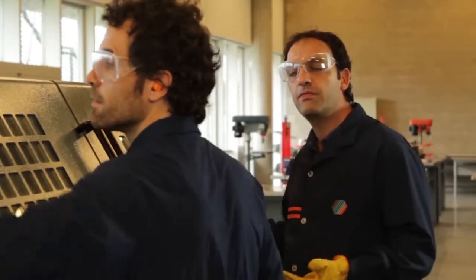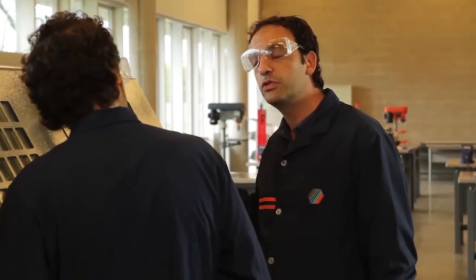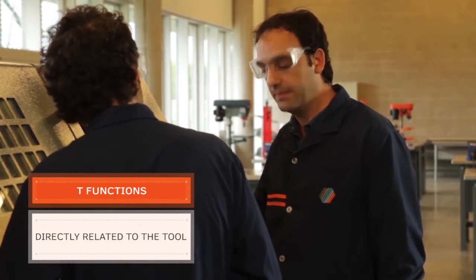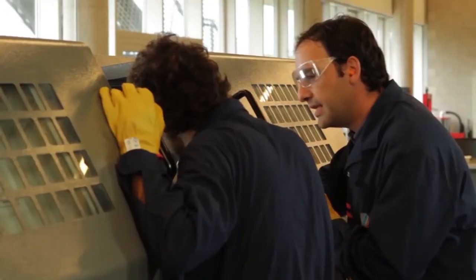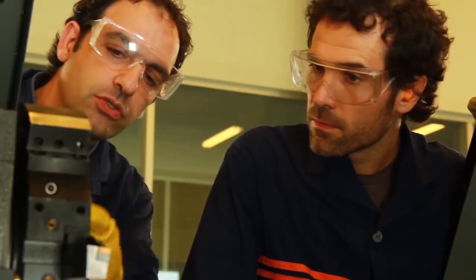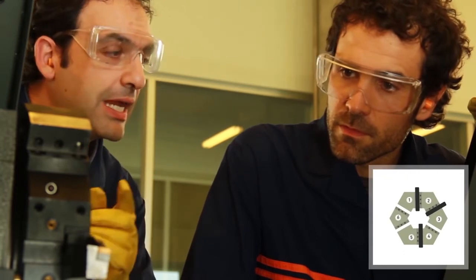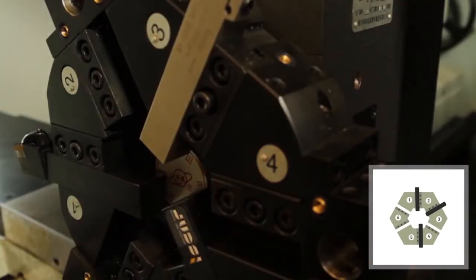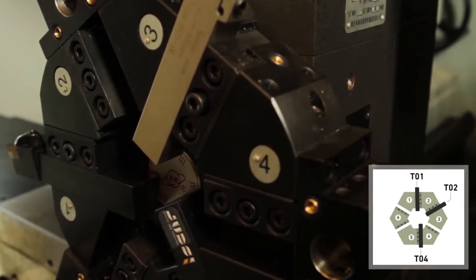Well, so we have seen the M functions and the G functions, and now we just have the T functions. The T functions are directly associated with the tool. I'm going to show it to you on the turret. Okay. The T functions have two assigned numbers, which are directly related to positions inside the turret. Can you see the numbers inside the turret? Yeah. Well, when I talk about the T01 function, what I'm assigning is the name of the tool located in the position 1 of the turret. All right. T02 is that which is found in position 2. T04 is located in position 4.